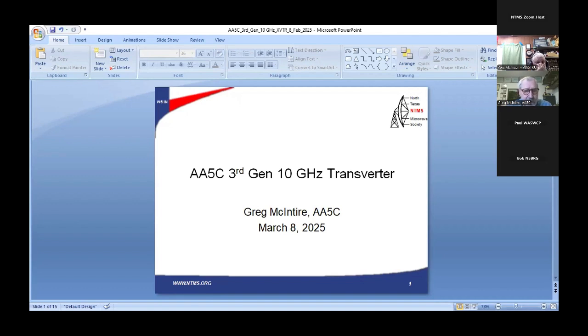I wanted to use a good 10 megahertz OCXO reference so I'd have stable operation from that, and also make an easy transition to a GPSDO if I have that in hand out in the field. Then build the W1GHz 10 gigahertz transverter board for the basic low-level input and output sections, and then add LNA and PA to get good system performance. So that's the approach I took.